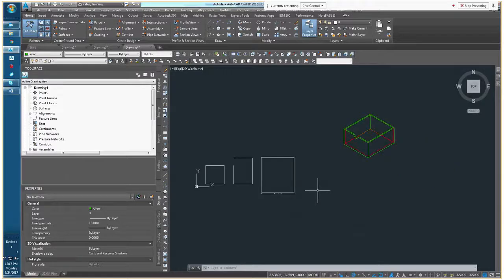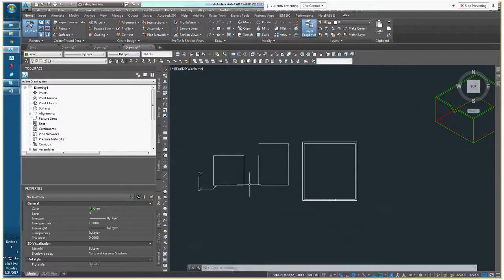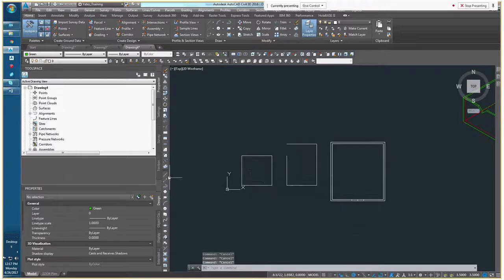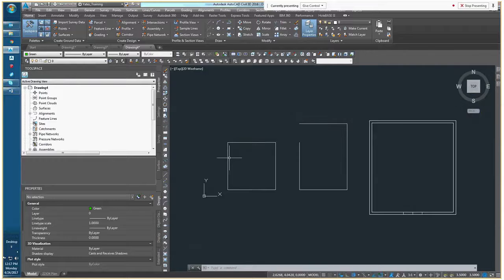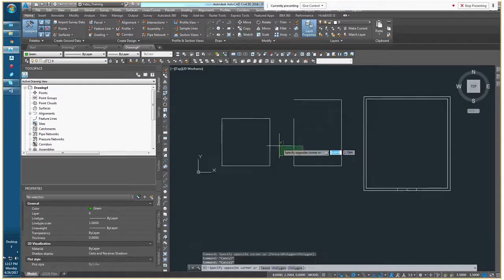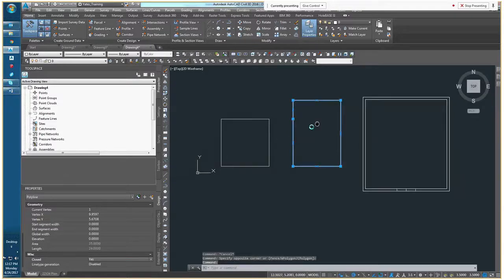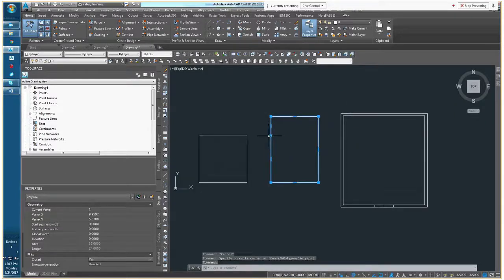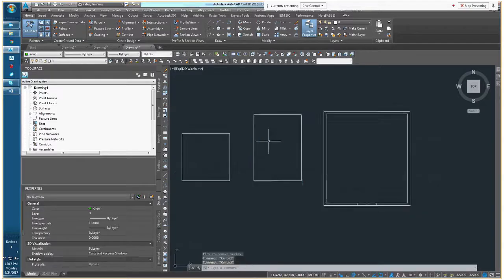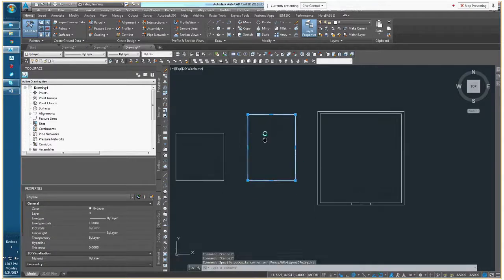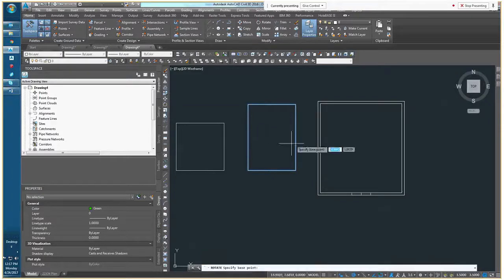So when it comes to rotating based on a reference, we're using our modify toolbar, which is this one right here. The rotation command is right here. And just using it, let's go to the polyline, and we'll close that real quick. I'm also going to remove these extra vertices. All right, so we have a nice little rectangular polyline here, and I'm going to select the rotate command, and I'm going to select a base point to rotate that.